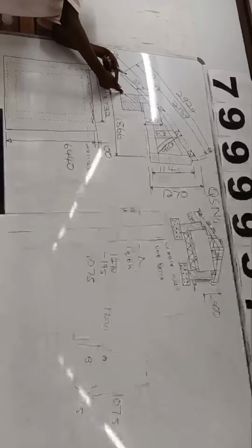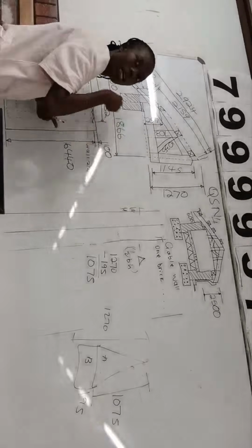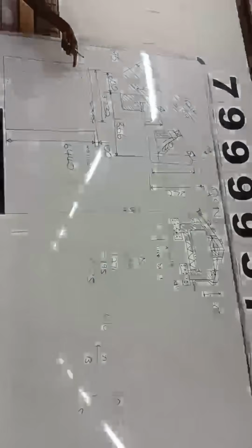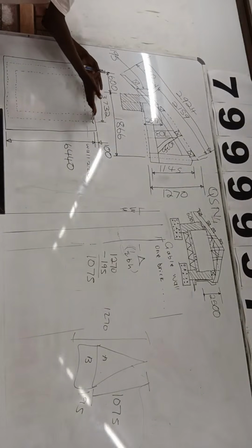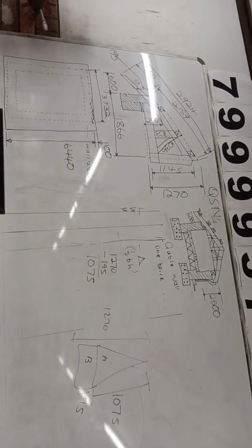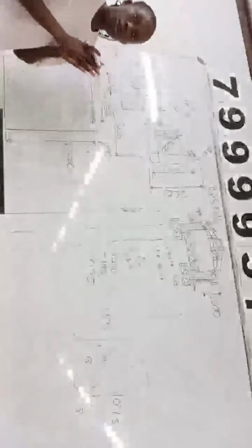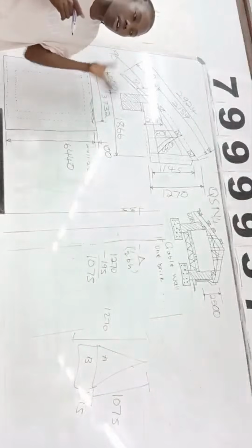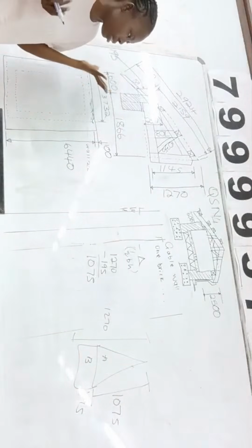This is your gable wall. This is where it starts. And remember, this is just the half truss. There is also the other part again. So whether you take 3732 or you decide to say 1866 times 2, it's fine, okay? But for you to understand, at least you know both ways. If you forget which one to do, let me try 1866 and see if it gives me the same result.